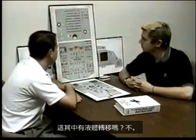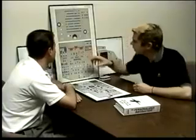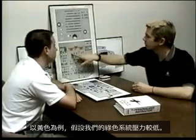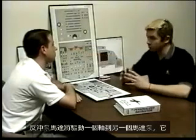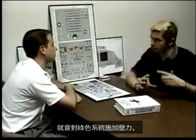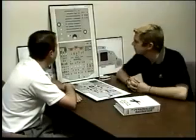Is there any fluid transfer with this? No, there's 2 reversible motor pumps on here, and the yellow, for instance, let's say we have a low green system pressure. The yellow system will drive that motor pump, it'll drive a shaft, the reversible motor pump will drive a shaft to the other motor pump, and it will then pressurize the green system. So there's never any exchange of fluid.